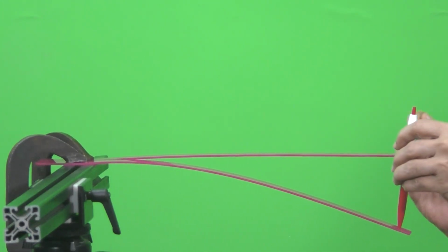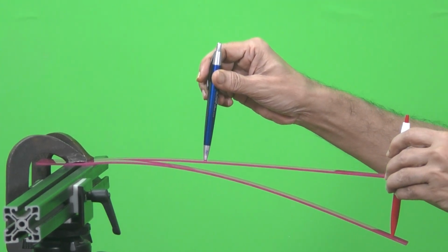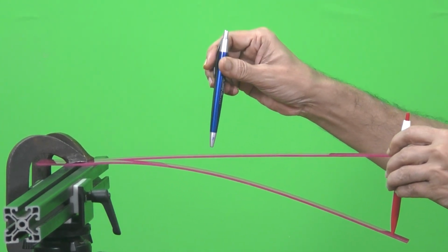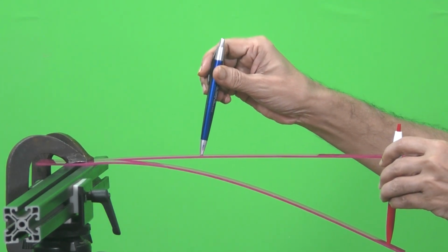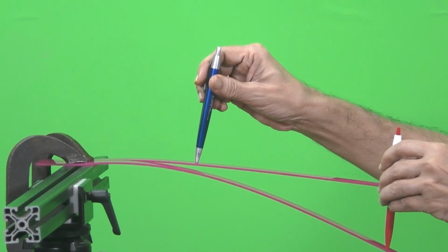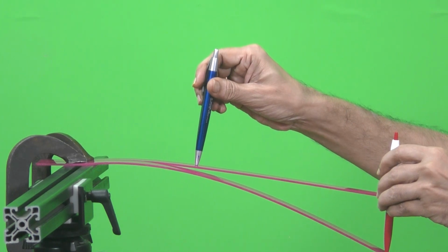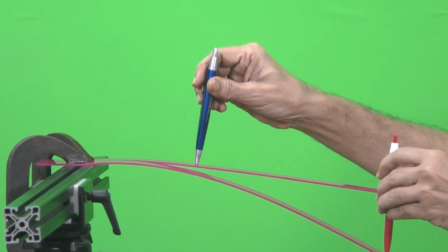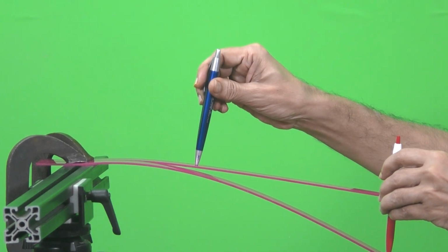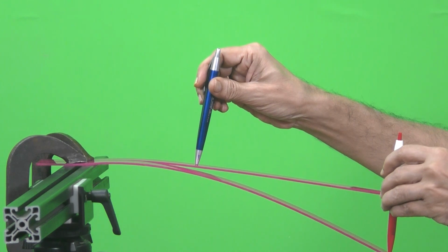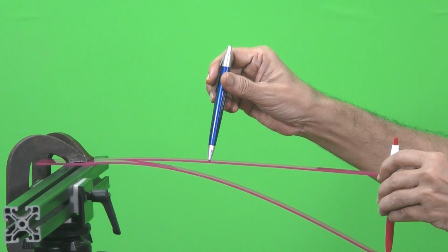Now, I take this beam and I apply load somewhere in between. Technically, I have no load on this section. When I apply the load, I want people to recognize what is the deflection up to the load application point from the fixed end and what happens after the load application point to the free end in the second beam. So, this section remains straight but rotated.